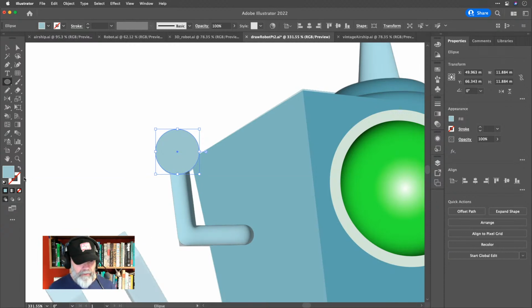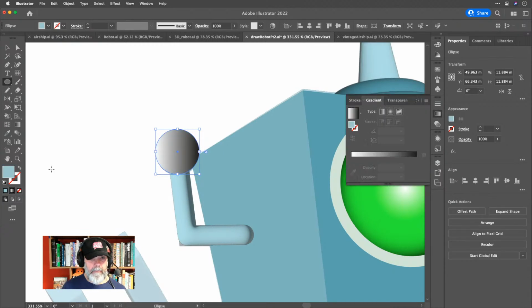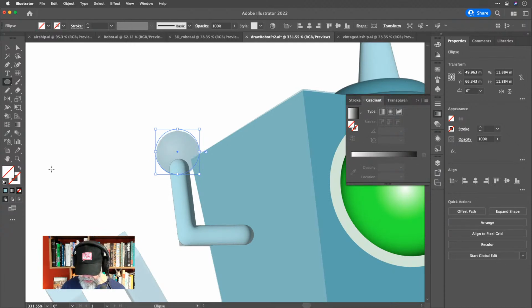All you need to be aware of is which one of these two things here, the solid square representing the fill and the hollow square representing the stroke, is in front. That's called having focus. It means that you can apply different things. If I hit the period key on my keyboard, you can see straight away that I get a gradient. In fact, comma, period, slash on the UK keyboard or American keyboard for that matter will apply these things. So comma is solid color, period is gradient, slash is none. See that? Nice and easy.